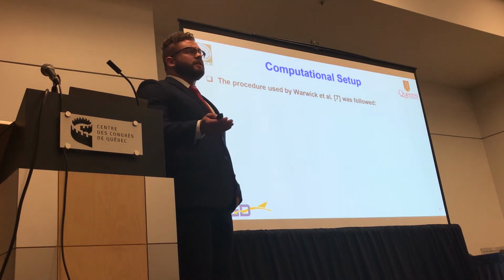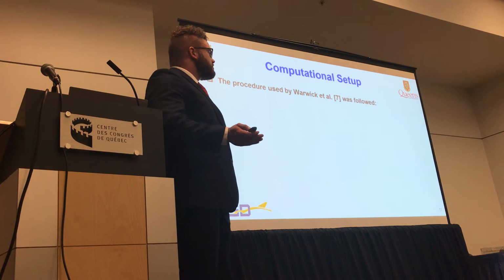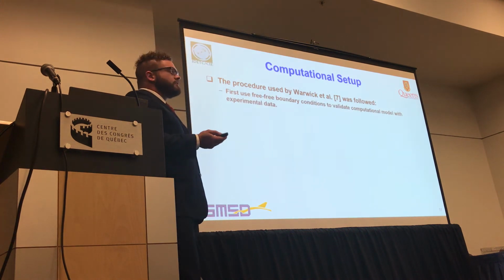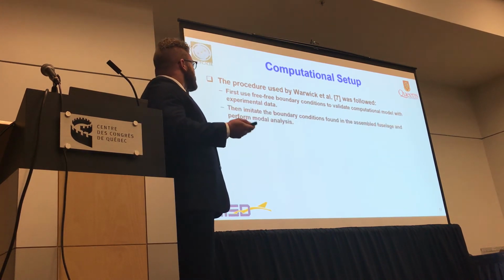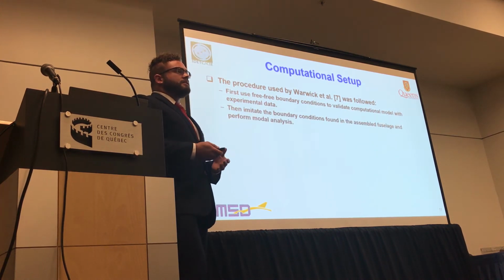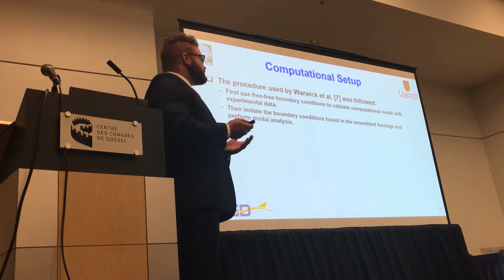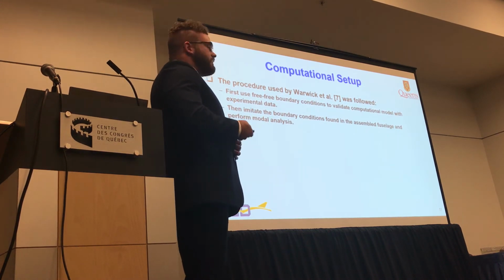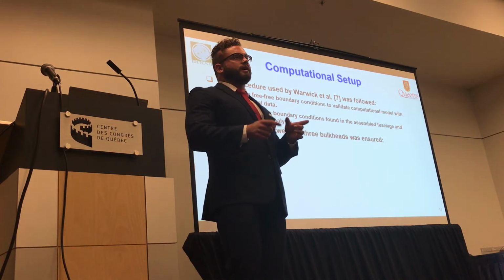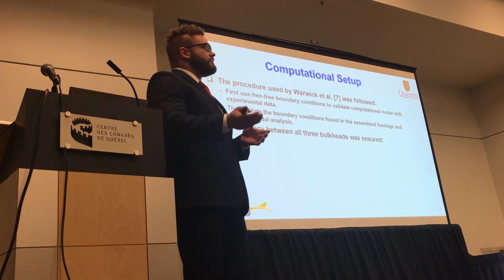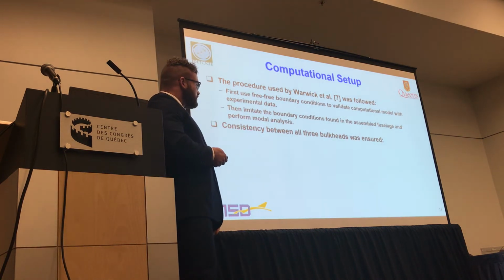So I used the same computational methodology that I proposed in my journal publication. I first used free boundary conditions to validate the computational model with the experimental data. And then I moved on to imitate the boundary conditions found in operation, and then performed the modal analysis again. And I investigated the frequency range of concern, which is the engine excitation frequency.